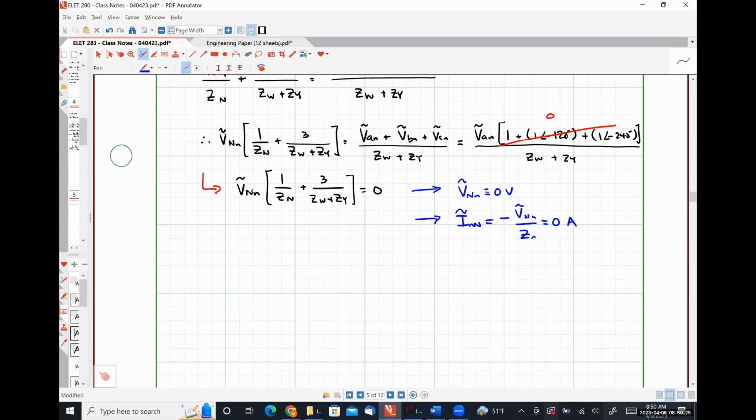It's used because not all systems are perfectly balanced, but what we're going to find is that it just carries a very, very small amount of current. All of the imbalance is going to be carried in the neutral conductor. And so that's why it can be sized significantly smaller than our transmission line cables, because it doesn't have to carry as much current. So that's literally the reason why it has a different set of specifications in the electrical code.